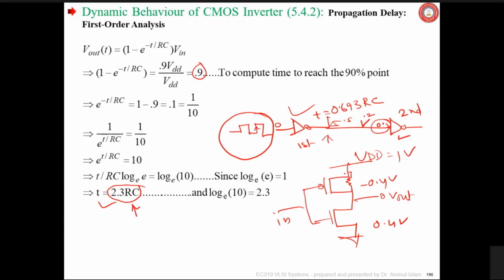And we have seen that MOSFETs are modeled as finite resistance in the on state, and in the off state it may be considered as infinite. So this Rp, while charging, when the output is rising. When the output will be falling, this point is falling, then Rn. Understood? So the resistance of NMOSFET and PMOSFET can be varied. How?